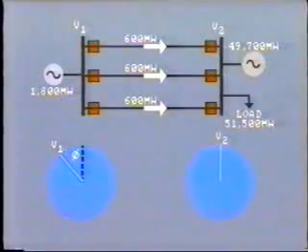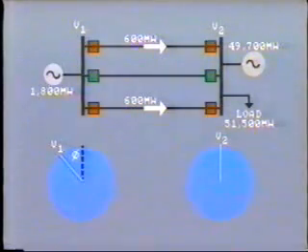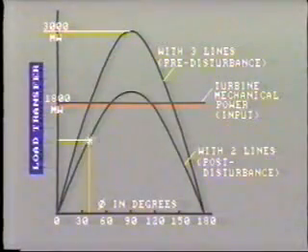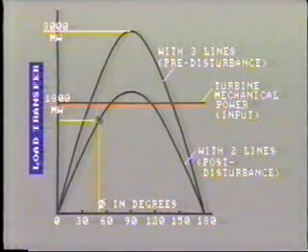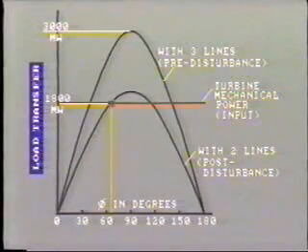Once again, consider the case where a system disturbance causes one of the lines to trip. As before, the instantaneous response is for the amount of power transfer to reduce and the rotor to accelerate from this point to the equilibrium condition again, which is now about 65 degrees.